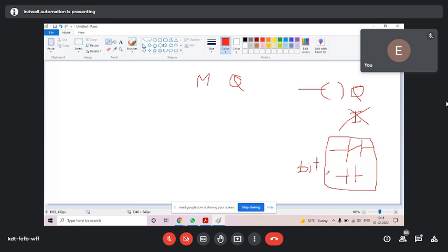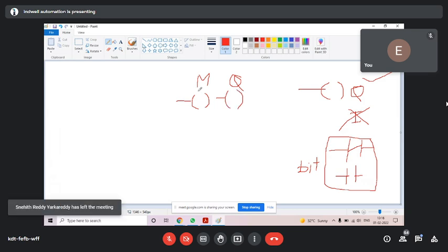Just now I told you: input address, output address, flag address. So in NO and NC, you can use any bit address. But in coil, from now, remember, you can use flag address too. So flag address and output address both can be used in coil.